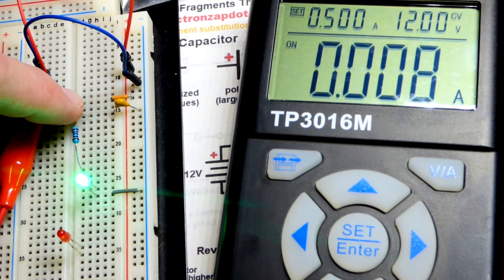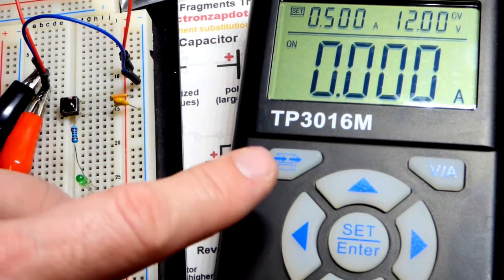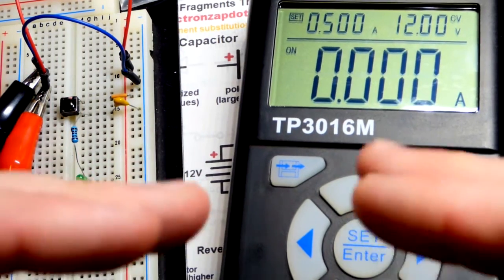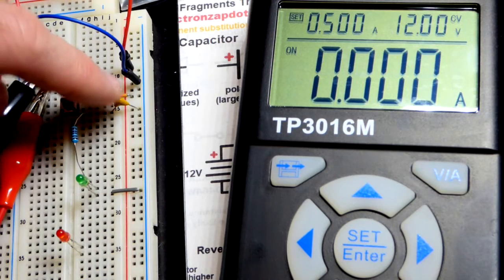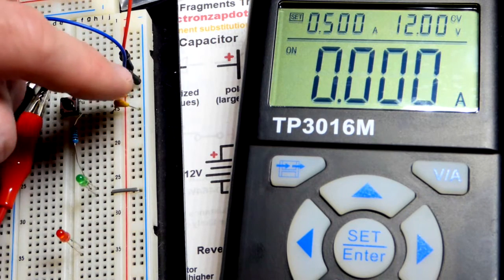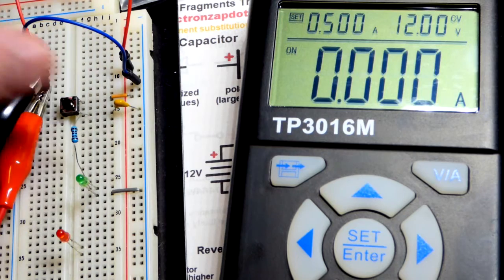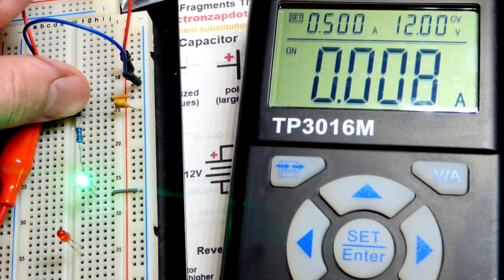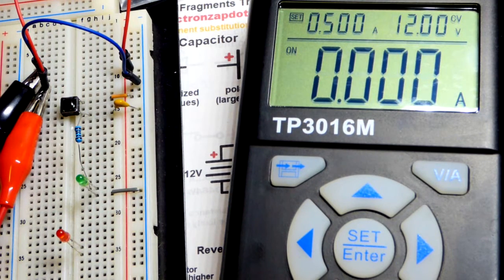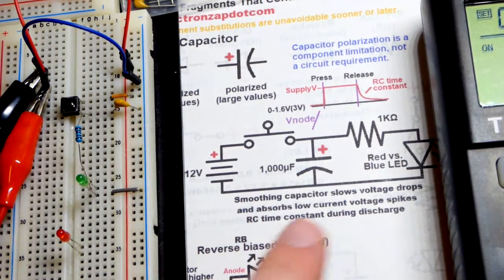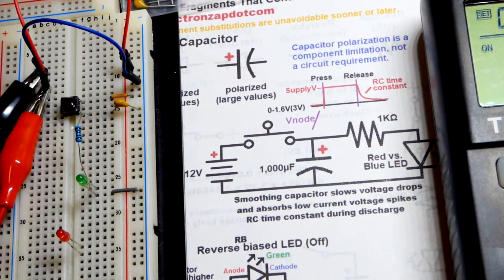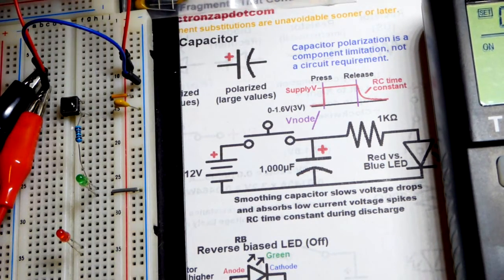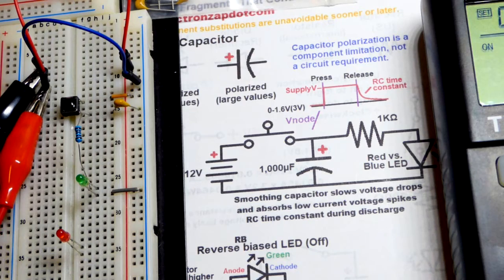So that would be called a smoothing capacitor. Sometimes these power supplies kind of have a little ripple. Their voltages change a little bit. A capacitor like this will probably be able to pick up the slack and hold a steady voltage like that. So there are uses, that's why you'll see capacitors like that. In this particular circuit, it will not fade off the LED like the large capacitor did nicely. So again, when you see circuits like this, pay attention to their electrical properties more than anything else, because odds are you're going to have to make a change.